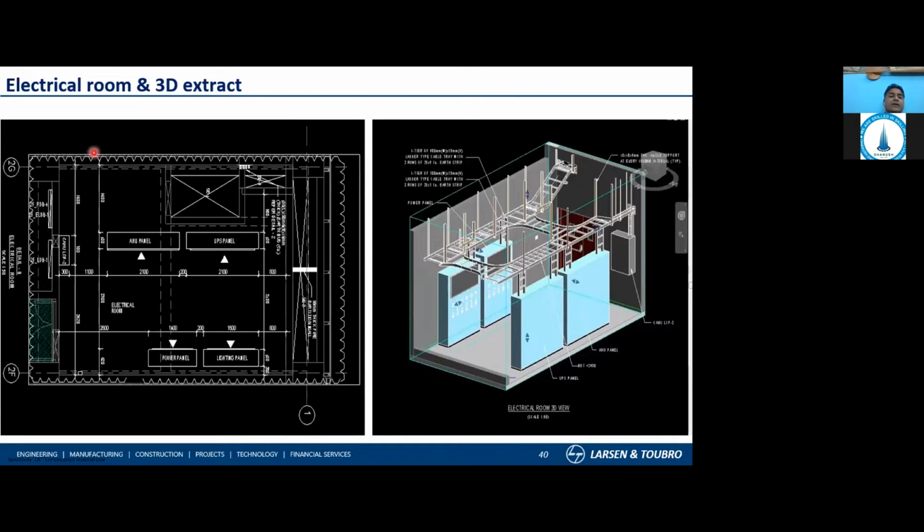Once that is done, we get into the rooms, where on a 2D drawing we plan locating the panels with the clearances. You can see here, this is the front side of the panel. When I keep the panels facing each other, I need to follow the minimum clearance. And these are the cutouts and shafts which I got to take the rising main and the cable trays. All these things are well coordinated with the dimensions clearly specified, and I need to demonstrate why I want this much space with all these dimensions, and only then does everybody accept.